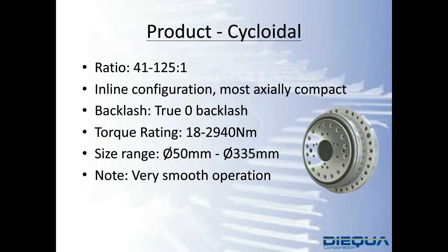The fourth gear technology that we're considering is the cycloidal unit. This particular unit uses an intricate design in which you have oscillating eccentric bearings creating 2 plates that are transferring motion on what we consider a transfer member, and it allows for a set of needles to walk the circumference of the housing which supports the pins, right?